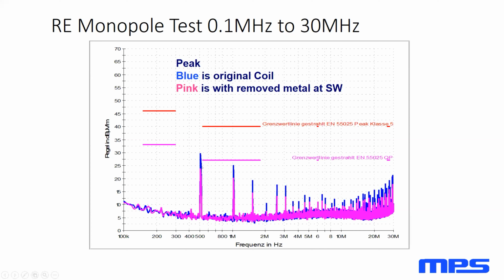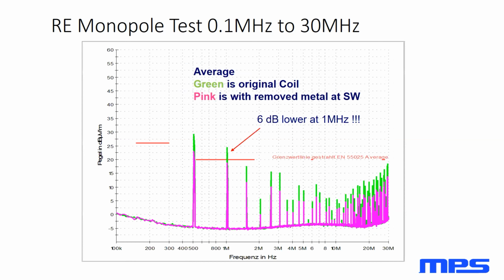And the other thing I'd like to point out, these particular results in this power supply are being done without spread spectrum, and you can see that because these are very distinct frequencies. It's not the spread out version that you would see with spread spectrum. So if we needed to pass EMC, let's say we were failing further out, one thing might be to take a look at that inductor. Another thing might be to add spread spectrum, and that's all the variation you might need.